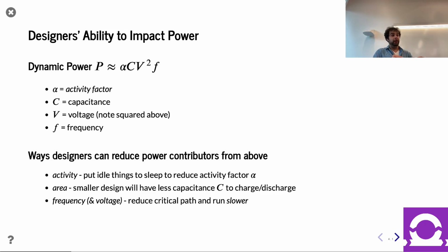Each of the transistors is smaller and has less capacitance, but because of the decrease in size of transistors versus the increase in number of transistors, it washes out and you end up with roughly the same capacitance. So for a given amount of area between different process generations, and this is a hand-wavy thing, capacitance is similar. As a result, as a hardware designer, that's going to be one of the ones that's harder for us to change.